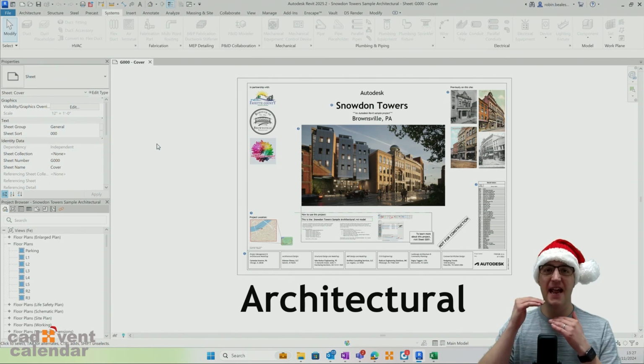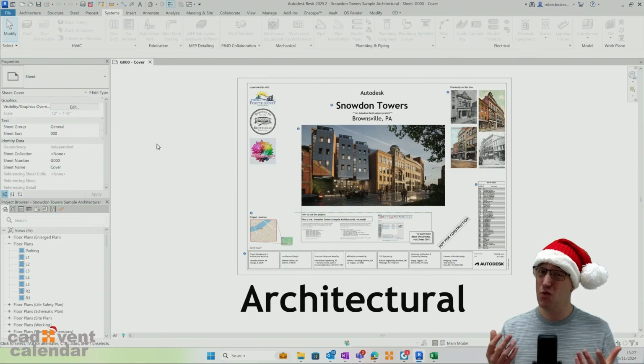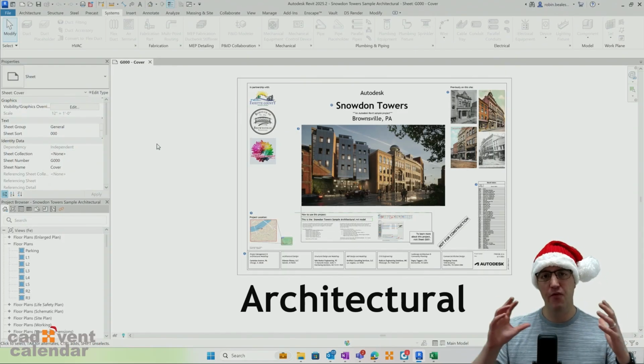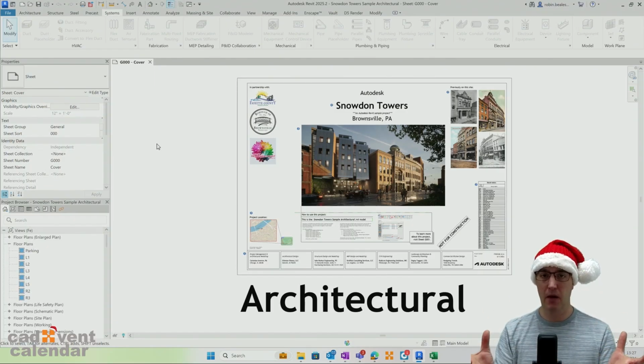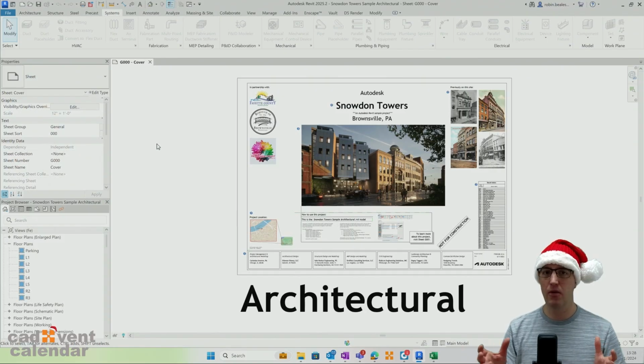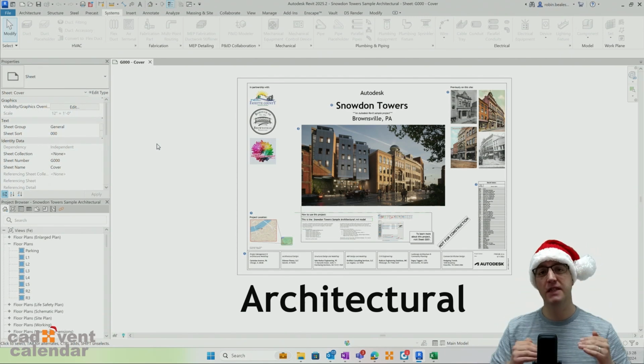This is what allows us to navigate through a Revit file, which is much like a real building, split up into lots of different levels, each one of those levels having a number of different views relating to it. For example, the ground floor, you might have a general arrangement drawing, so your GA. You might have a furniture layout for FF and E. You might need a typical fire layout or an area plan or umpteen other different views for each individual level in the building.